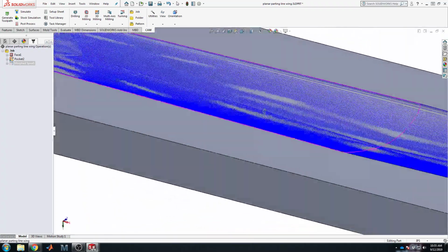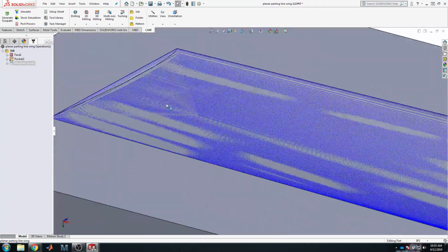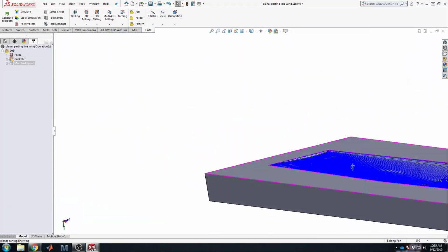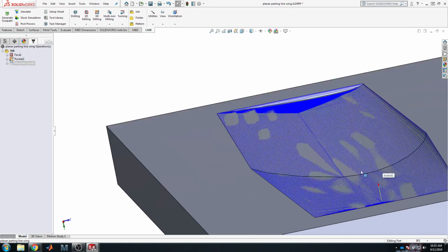Now imagine if we hadn't done the roughing pass at all on this very deep cut mold. That little 1/2 inch wide ball mill would be trying to plow through however deep this is, 2 inches of MDF, 2 inches of foam, in addition to cutting at the surface. You don't want to do that all at once.